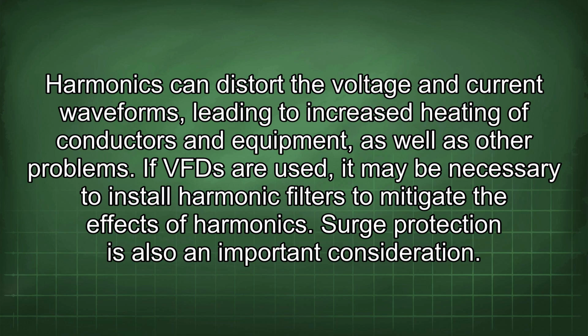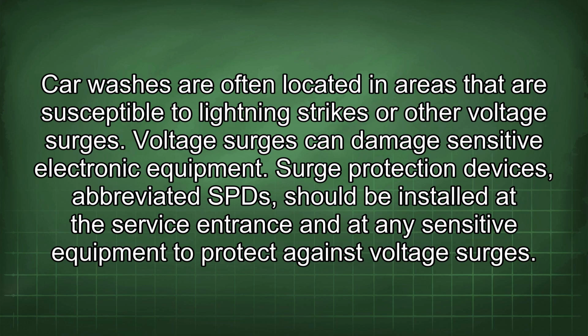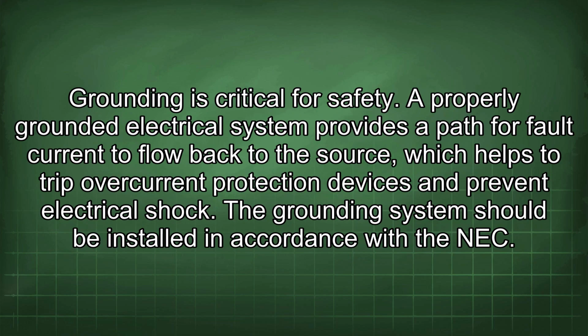Surge protection is also an important consideration. Car washes are often located in areas that are susceptible to lightning strikes or other voltage surges. Voltage surges can damage sensitive electronic equipment. Surge protection devices, abbreviated SPD, should be installed at the service entrance and at any sensitive equipment to protect against voltage surges.